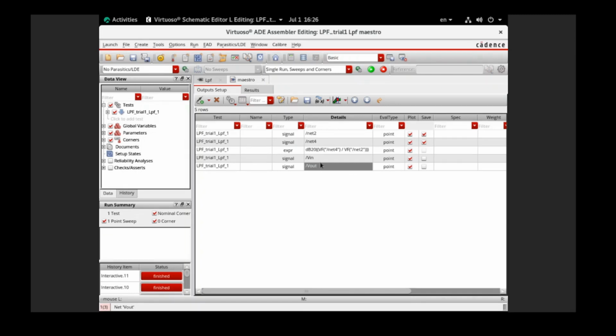Here the circuit is quite simple, so it's really easy to remember. However, it's better to label the Y or the signal properly, so in the simulation we can easily observe them, and we should save them when we run the simulation. Now let's delete what we don't need. You press the signal that you want to delete and you press Ctrl to choose all the signals that you don't want, and here you can choose delete.